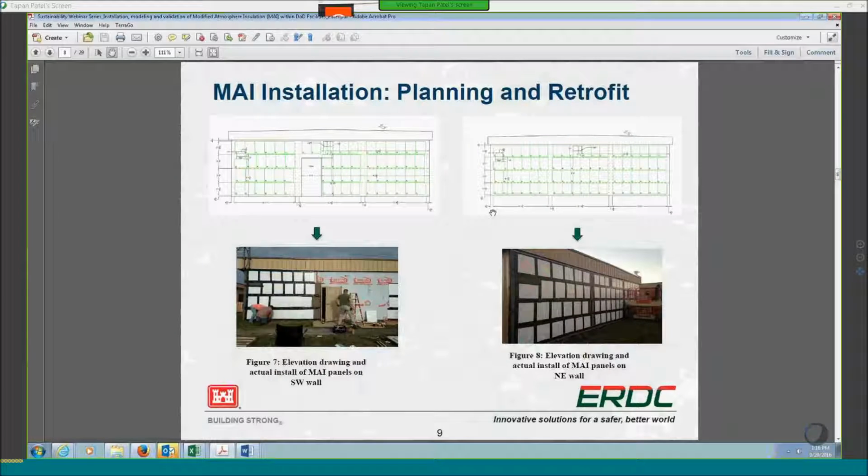So taking a step back, our first goal and challenge to some extent was coming up with a plan to install these. Compared to traditional polyiso or fiberglass, it doesn't make sense to put this in the cavity, because the only purpose that will serve is further enhancing your thermal bridging. We really wanted to cover the exterior of the envelope and reduce that amount of thermal bridging.